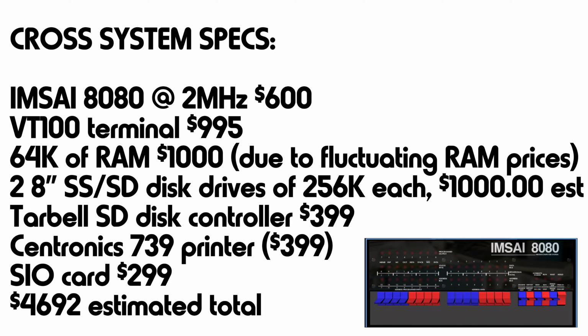Well, in our case, since we have an 8-bit processor with a 16-bit address bus, we have a maximum of 64K of RAM that we can put in the address space. And doing 64K of RAM on a machine in 1981 would have set you back roughly $1,000, which is ironic, because if you had waited into the first 6 months of 1982, that number would have been sliced in half at least, due to the introduction of 64 kilobit